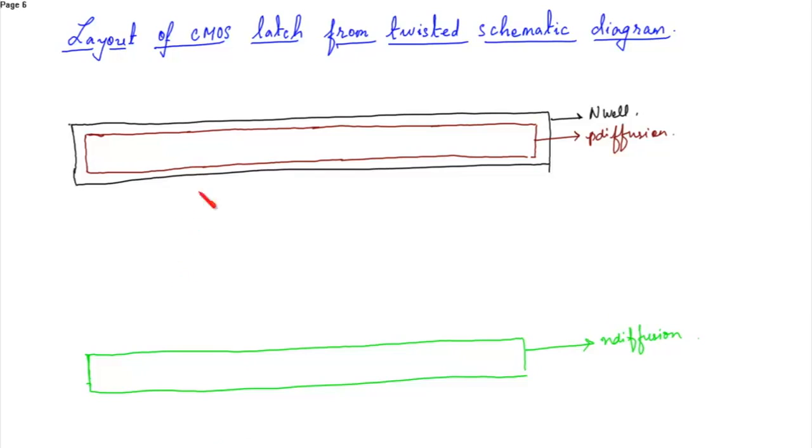So first you have to draw the gates so that you can distinguish which part is the transmission gate part and which is the inverter part. So this is gate 1, gate 2. Okay, let's take the inverter gates first. Suppose this is inverter gate 1 and this is inverter gate 2, transmission gate 1, transmission gate 2. Similarly, mention the dots here just for your convenience. You will not draw like this in Magic, but just for your convenience.